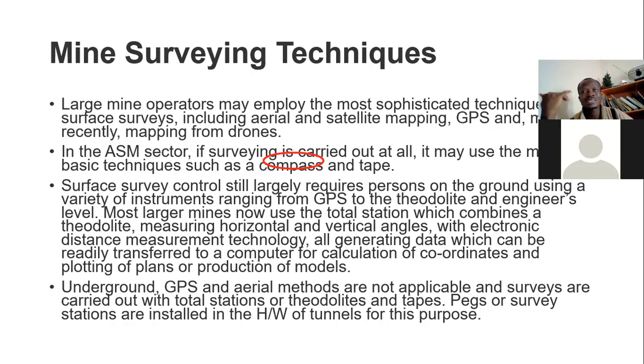You can't use any system that requires satellites underground. You're going to have issues. So as you can see here, underground, GPS and aerial methods are not applicable. The survey is carried out with total stations, theodolites and things. So here you need a surveyor.